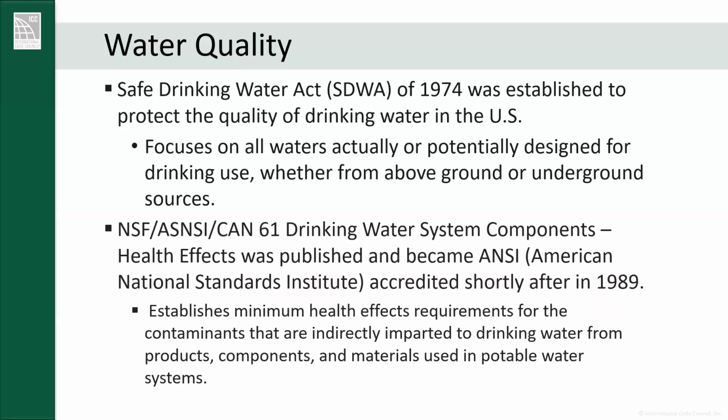So this applies to all finished products and all of the wetted components in the potable water system. So earlier I said that I was testing plumbing products. They not only have to meet the minimum performance requirements in the standard, but if it's a kitchen faucet or a lavatory faucet, they also have to pass the NSF 61 requirements, which means that it's a completely different test.